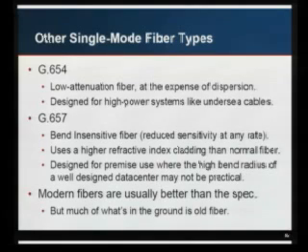And then the newest kind is called bend insensitive fiber, which it's not really insensitive, it's just less sensitive. But it's fiber that's designed for fiber to the home, office building type applications where you don't have the same engineering level that goes into a data center where you engineer your fiber all nice and neat. You have these installers who are used to pulling power cables through just by yanking it. So you need to deal with bend radius that is beyond what you might normally see.